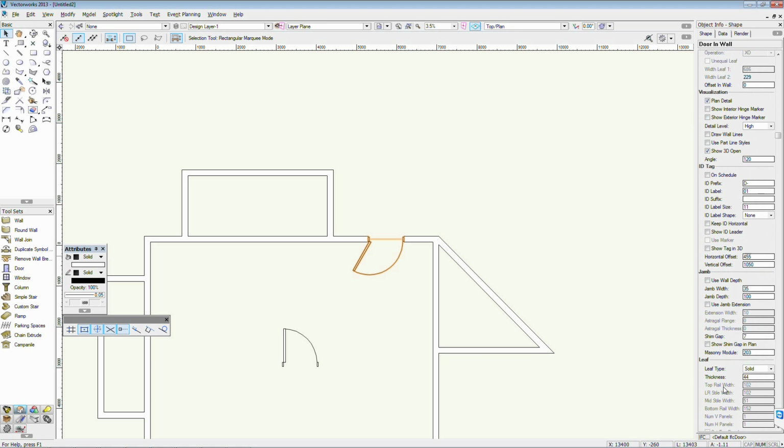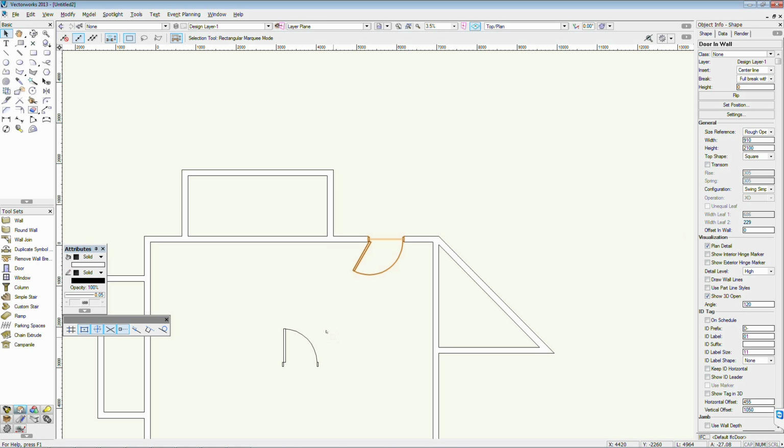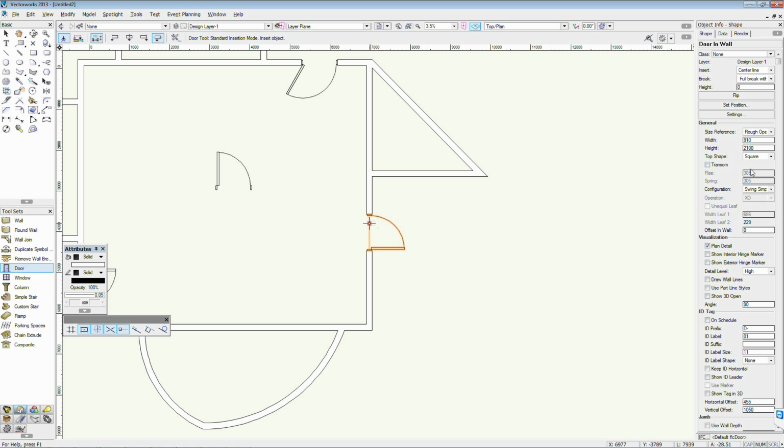Just be aware, obviously, when you change your door type, for example, if I put another door in over here, I'm going to make this a double door. What you'll want to do is change the configuration to a swinging by part, which puts it in 2, and then just in the width, just throw a ×2 inside there, which will make it back up to the regular size. The configuration has to confine by your width and height specifications at the time of creation, so obviously we just need to double that afterwards or before.